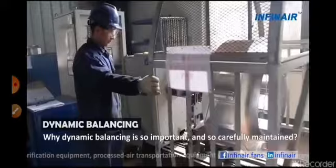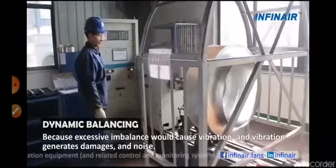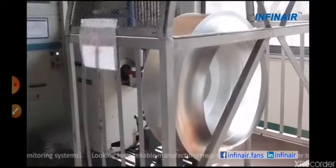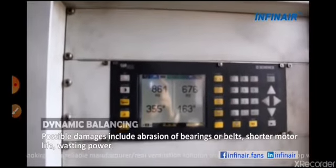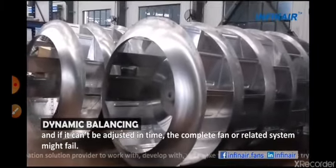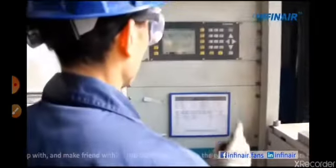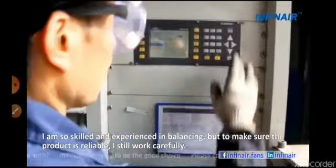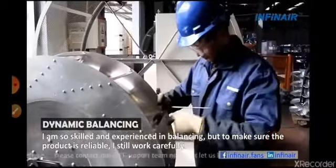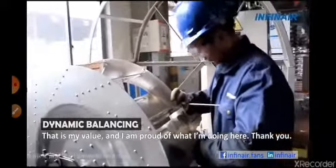Why is dynamic balancing so important and so carefully maintained? Because excessive imbalance causes vibration, and vibration generates damage and noise. Possible damages include abrasion of bearings or belts, shorter motor life, wasting power, and if it cannot be adjusted in time, the complete fan or related system might fail. I'm skilled and experienced in balancing, but to make sure the product is reliable, I still work carefully. That is my value, and I'm proud of what I'm doing here. Thank you.